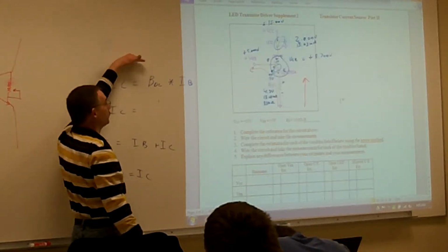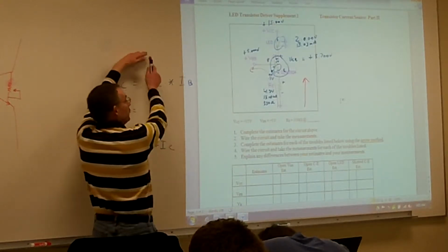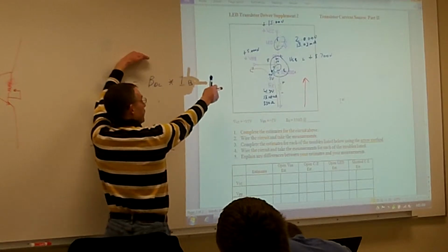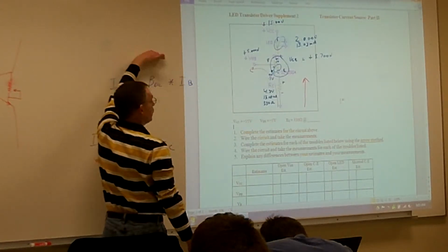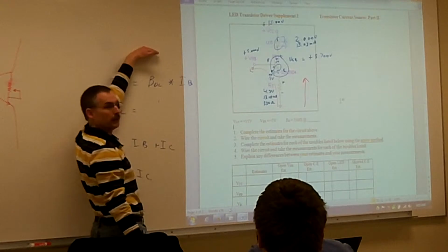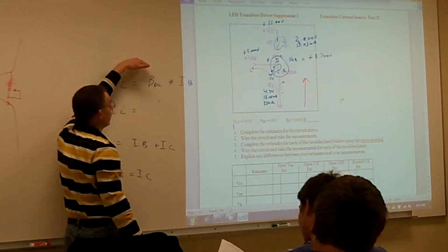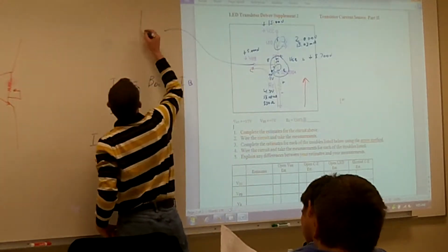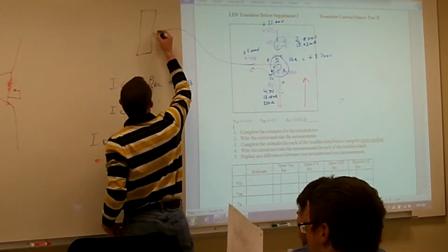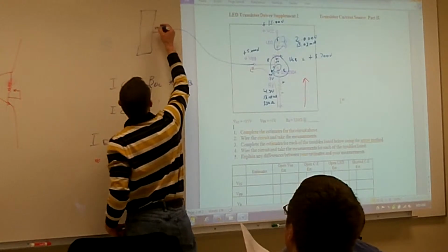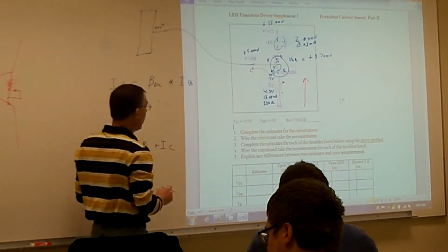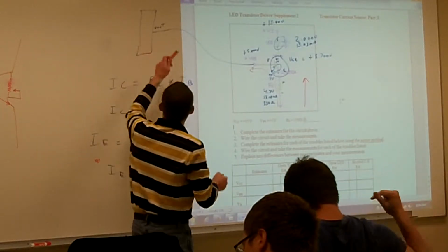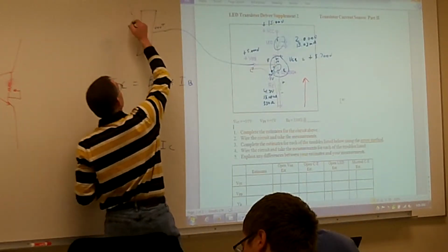Remember, that's what we're trying to do, is protect this output device here, because we want a very, very small amount of current going into it with a very high input impedance. The minute that transistor burns out, I probably end up burning out this one too. So I'm coming in, and we'll just say some digital chip or something, I don't care what it is, but this is kind of our V out of this one. It can't handle much current. All of a sudden that transistor burns out, it starts driving a lot of current, then this one starts smoking.